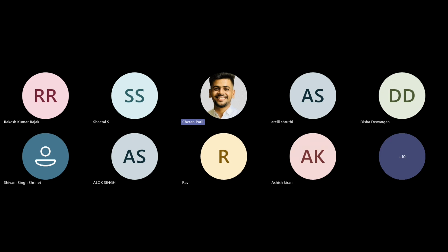That means some automatic variation will be done with respect to whatever values you mention over here. And the other method is you can just directly turn it off, which will help you directly define how many actual divisions you want in your body. Those two options are available. Auto time stepping is where you divide your load using three different parameters: initial time step, minimum time step, and maximum time step.